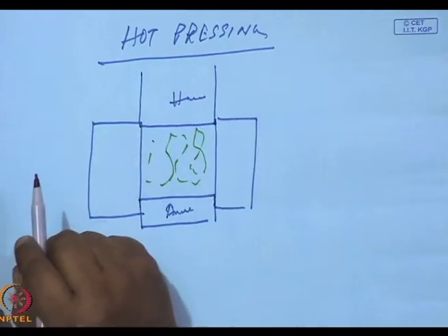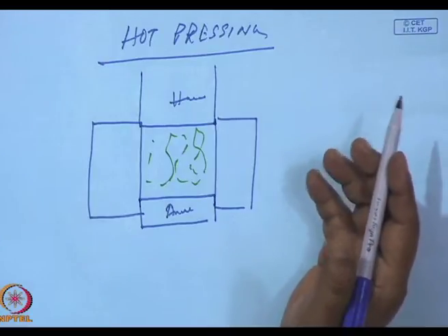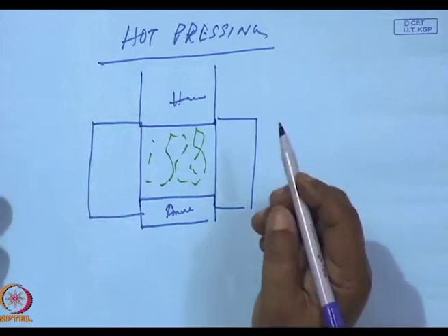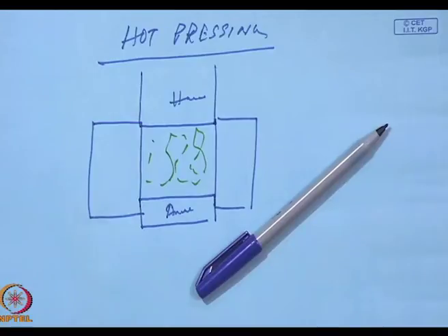You will say, how is it different from cold pressing? Hot pressing is required where the sintering rates under biaxial pressing or no pressing at all is very slow.